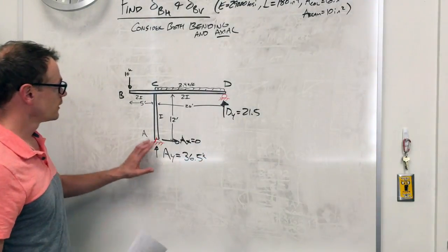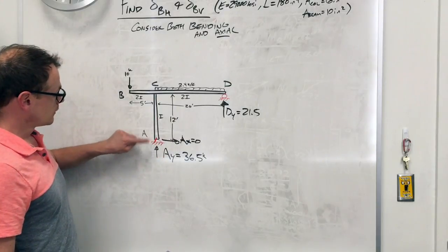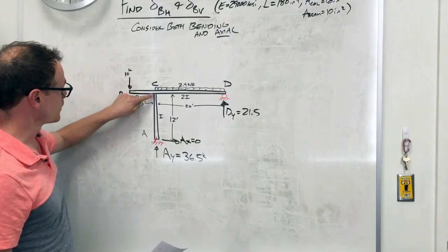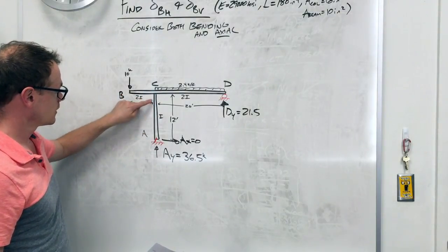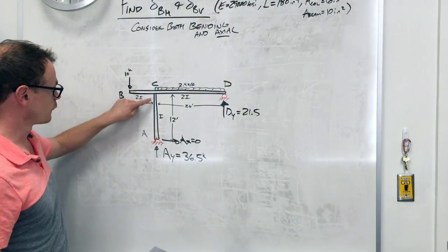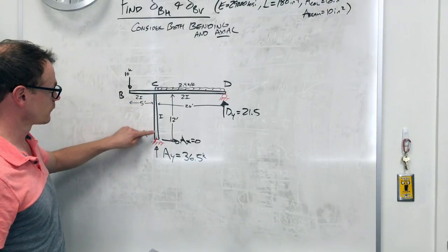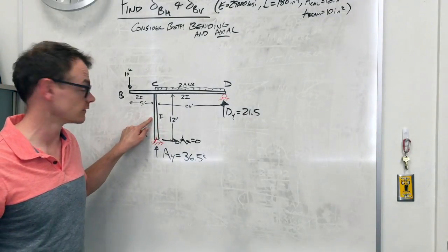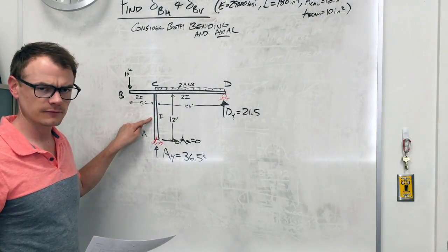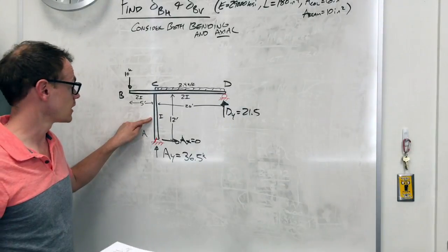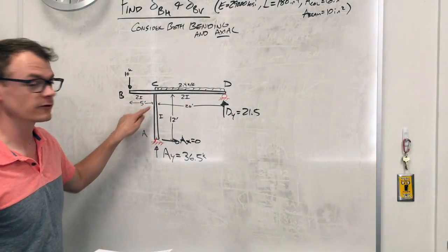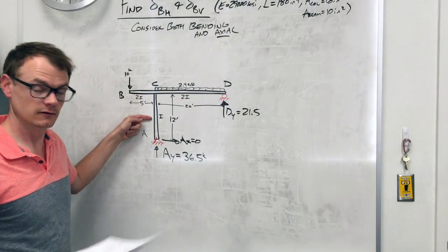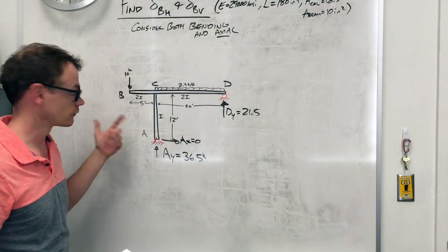Okay, so from here, the way that you're thinking about frames is this reaction is telling us that this column, since it's straight up and down, is transmitting the vertical load down to the pin. And there's no Ax, so there's no shear in this column, which is a little bit odd, but hey, how can you have shear? There's a roller over here. There's nowhere for this thing to react in the x and give any shear in this column. There's no applied load, so there's no shear.